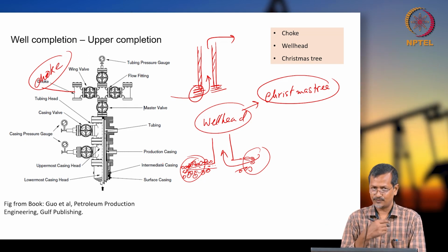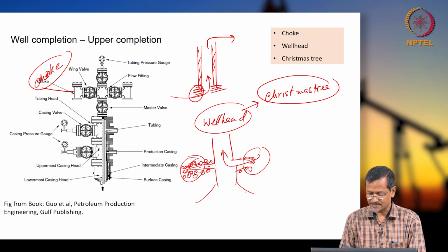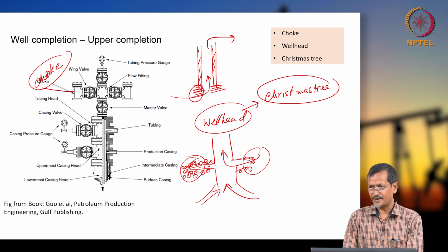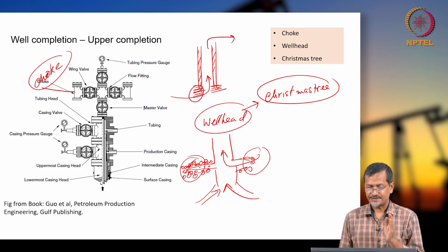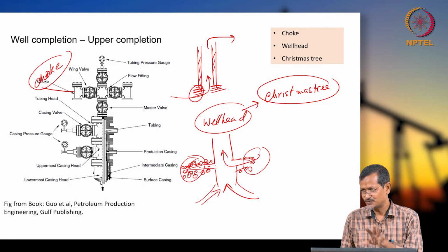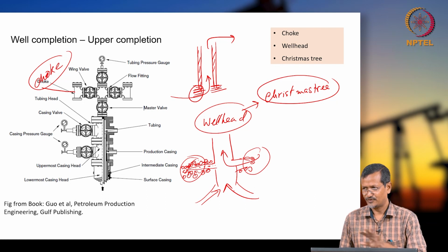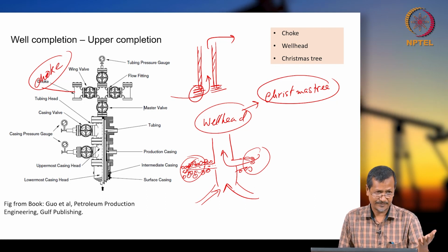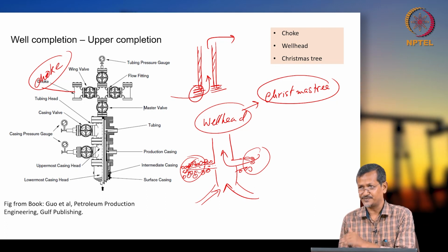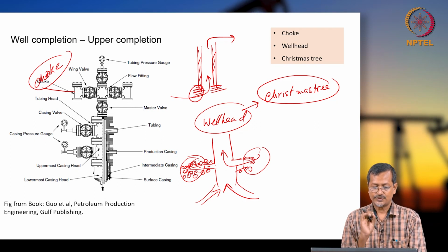Again, many times you suddenly want more production, so sometimes water coning will occur. Water will create a cone, so oil and gas will not enter, and rather more water will enter the wellbore. So you need stable production for a longer duration, one year, two years, so that you get less sand, less water, and economic benefit. But if you change it, you may get very high production today, but tomorrow it may not be so high. It will create many other problems. So you must have a controlling valve, because a controlling valve is required to control flow.